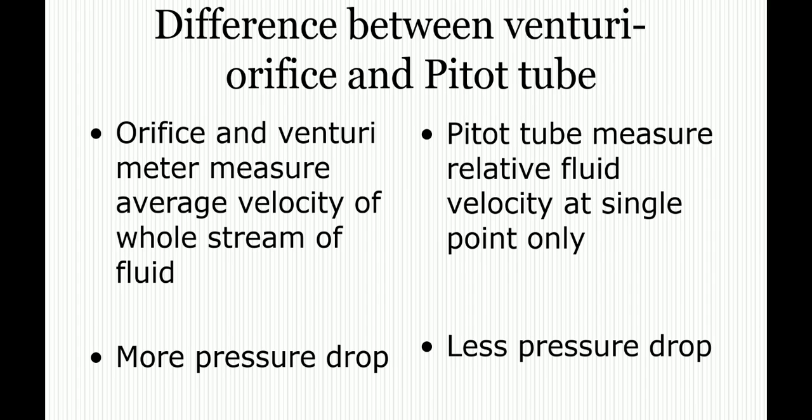Now the disadvantages: Pitot Tubes themselves cause more disturbance. So eddies within the pressure tube disturb the reading. And the second disadvantage is that they do not give average velocity directly. For gases the reading is extremely small, so for gases working at low pressure, some form of multiplying gauges must be used when you want to measure the pressure of gases.